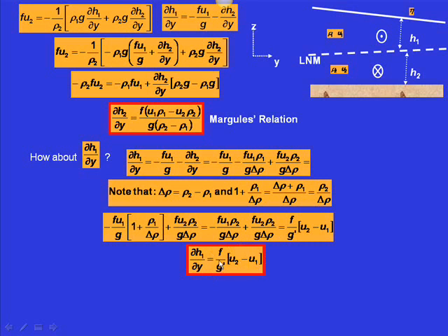This g prime we said was what? Internal wave? Not yet. No, square root of g prime H is the speed of the long internal wave, right? I hope you said it this morning when you woke up. You did? Good for you. But what's g prime? When you say square root of g prime H, you have to know what g prime is. It's the density difference multiplied by gravity, normalized by the density. And that's called the reduced gravity.